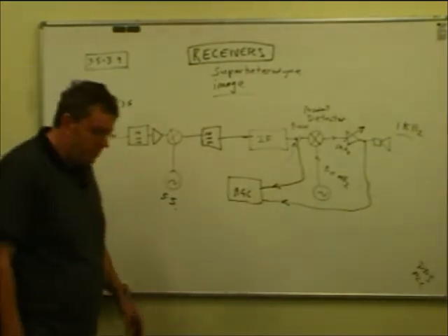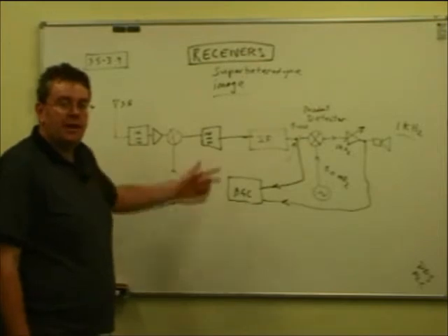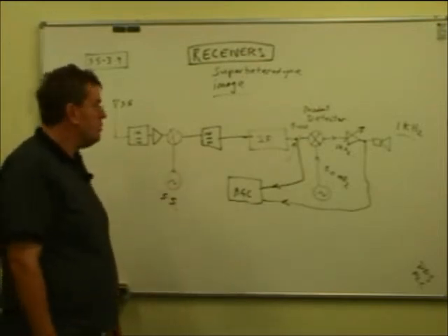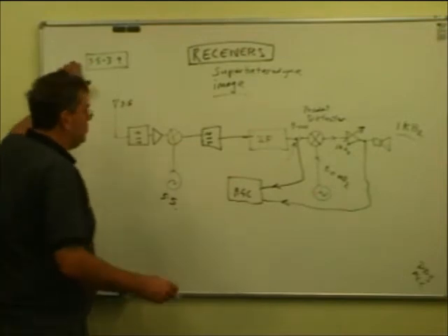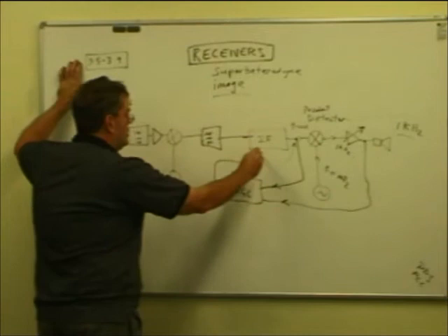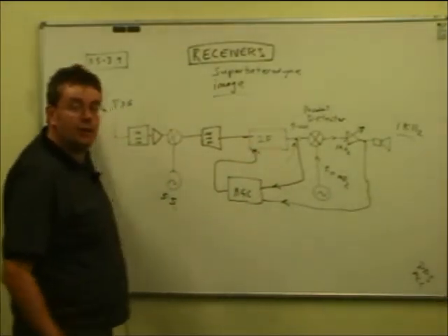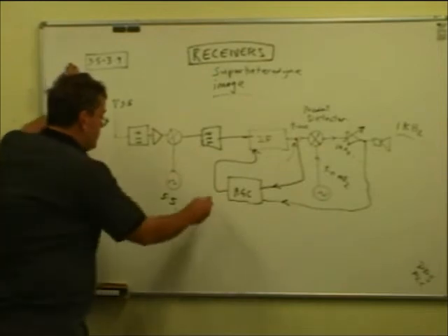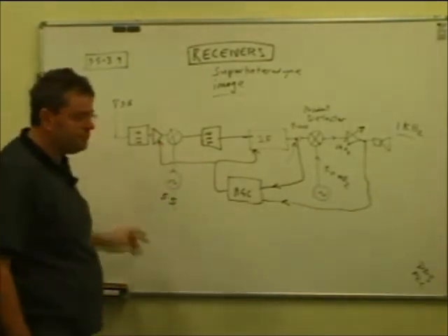It's basically measuring how strong the signal is coming out the back end of the receiver. And if it's incredibly strong, to avoid you getting your ears blown off, it will feed back generally to the intermediate frequency amplifier. It will turn down how much it amplifies. It will turn down the IF volume control, if you like. And some receivers will also reduce the RF gain as well.